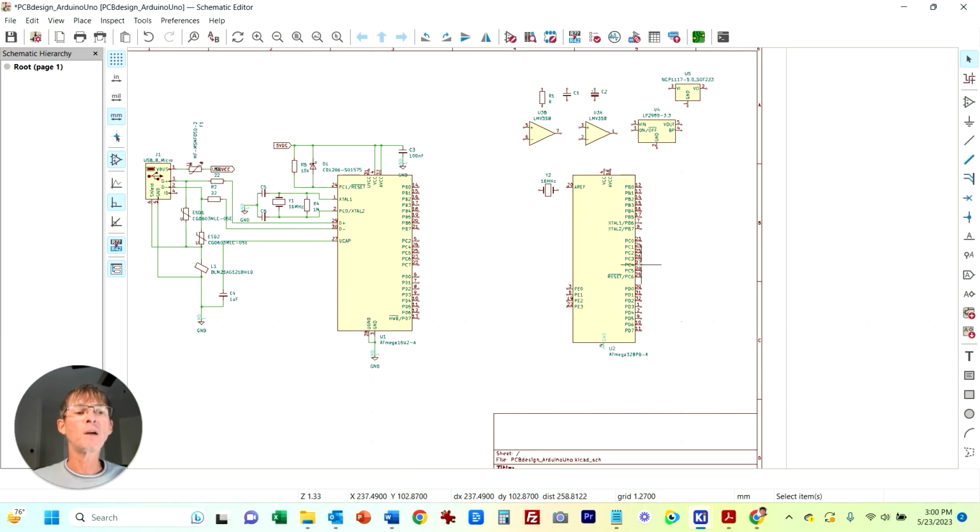Although these GPIO pins obviously go to the outside world, that's typically only on a DIY maker type of project. Most of these, for any type of commercial product that would really have consumers, are going to be internal pins. It's only pins that go to the external world that the customer could accidentally touch that really need the additional ESD protection.